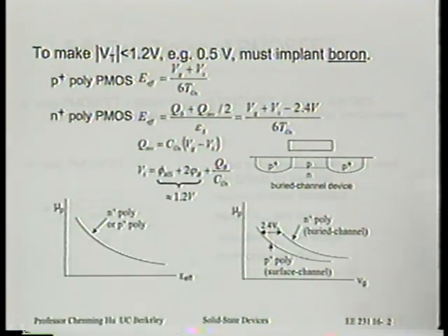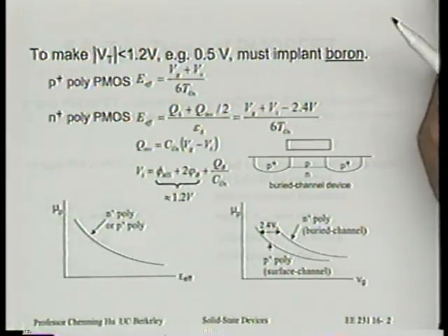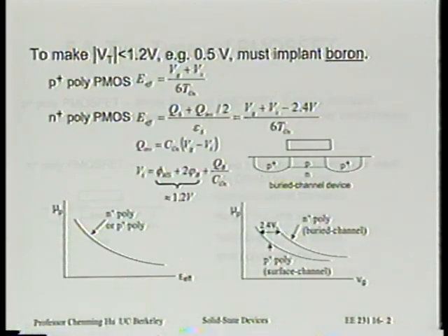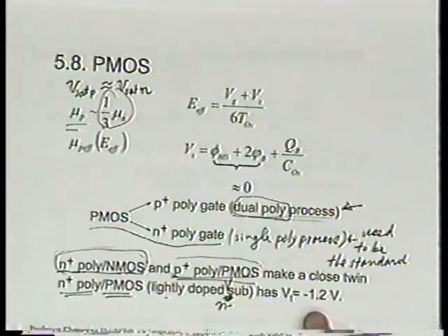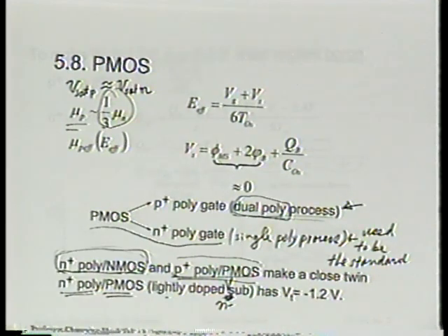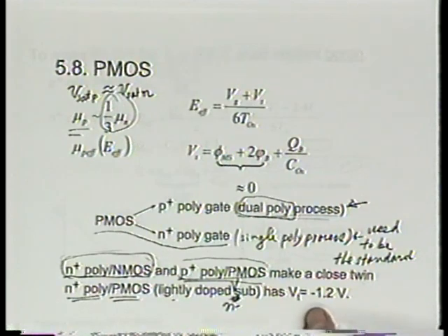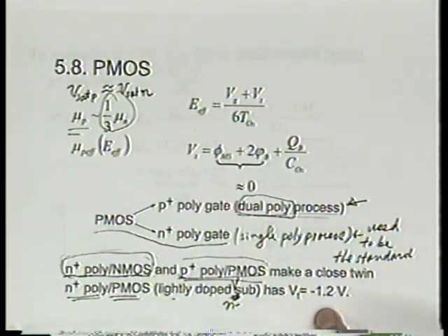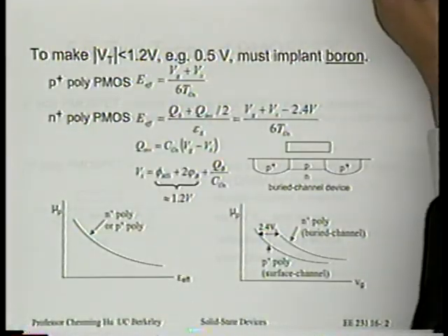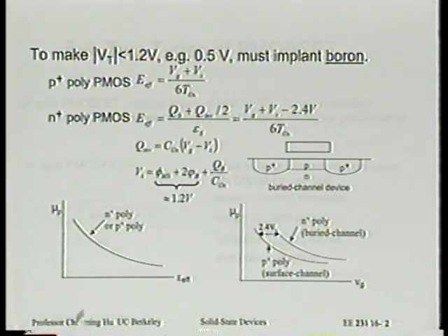By the way, it's very difficult to do that. That's why the industry has moved away from that. But when we are still making minus 0.7 volt transistor, that's the way it's done, all right? We'll implant some boron to bring the threshold voltage from minus 1.2 volt to minus 0.7, and that will be done, okay? And so we would implant boron in order to bring the threshold voltage down, okay? But when I say down, we mean less negative value, closer to 0, right?